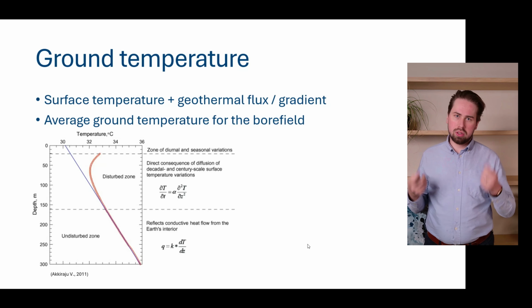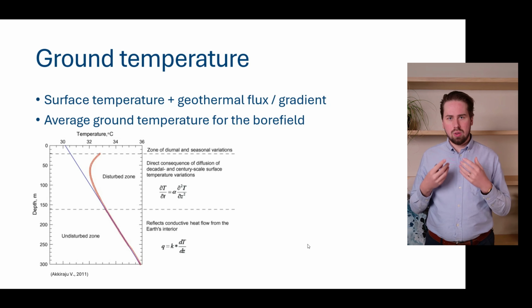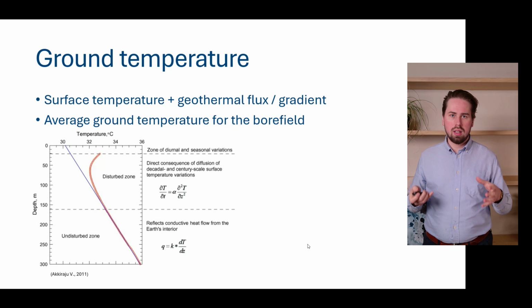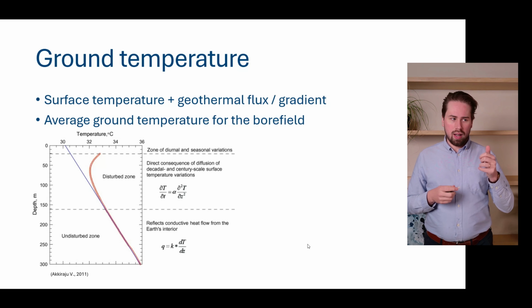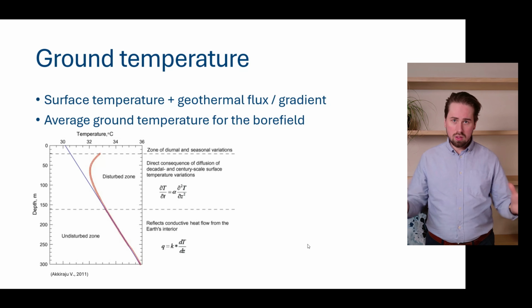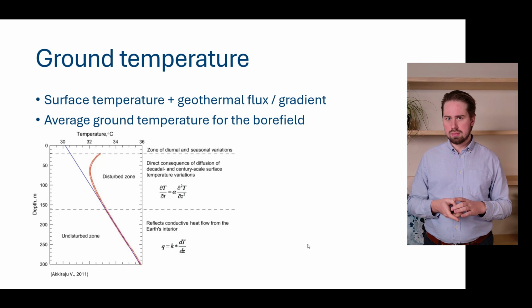So that's also important to keep in mind. What is your initial undisturbed ground temperature? Meaning, if I drill my borehole, I install everything, and I turn on my system, what is my initial temperature when the ground is undisturbed?